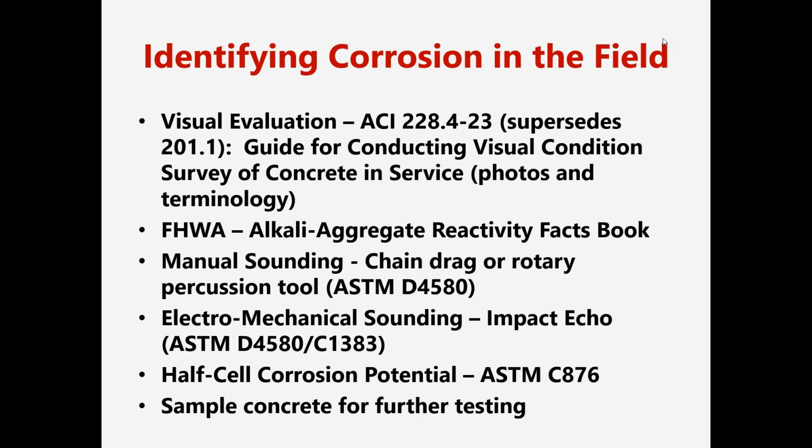ASTM D4580 talks about a chain drag. You can use a rotary percussion tool. 4580 also talks about some electromechanical methods like impact echo, which is specifically covered in ASTM C1383. It's kind of a little bit more of a high-tech sounding tool.